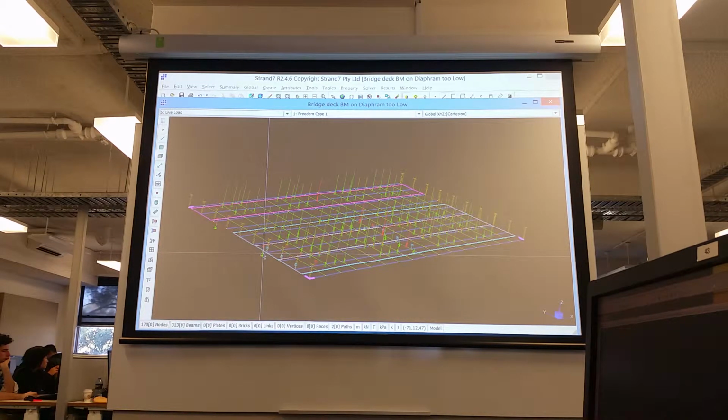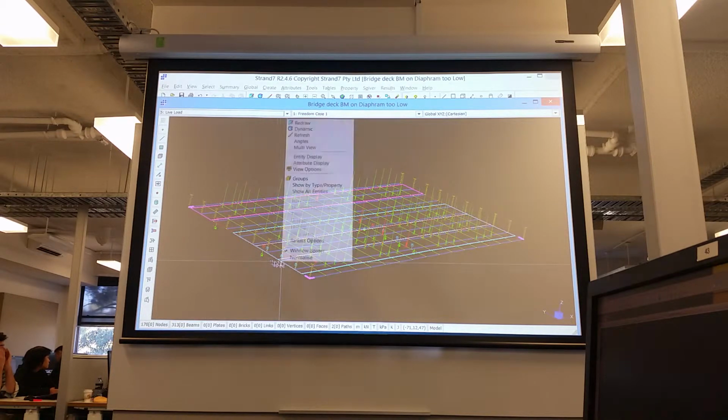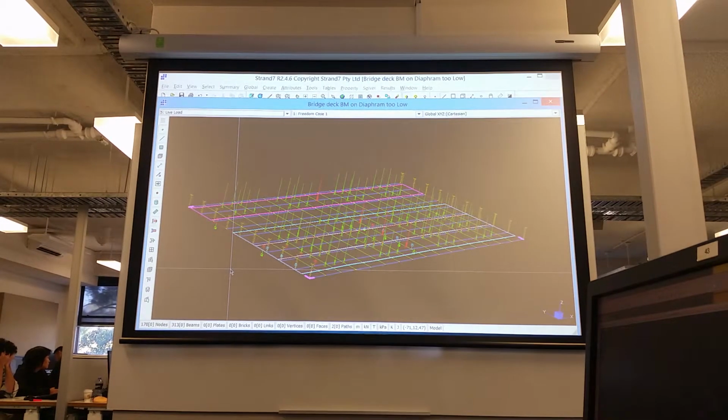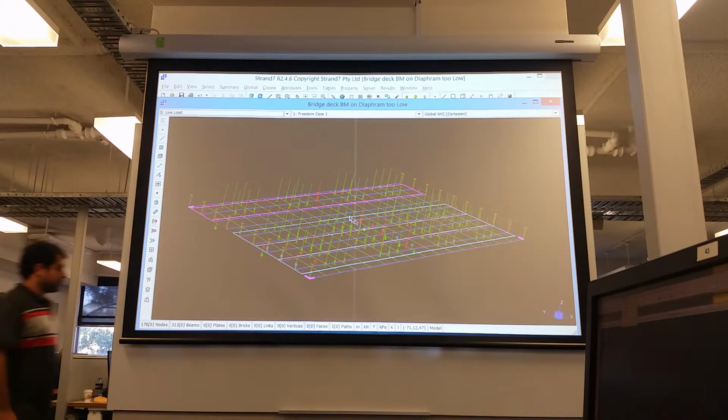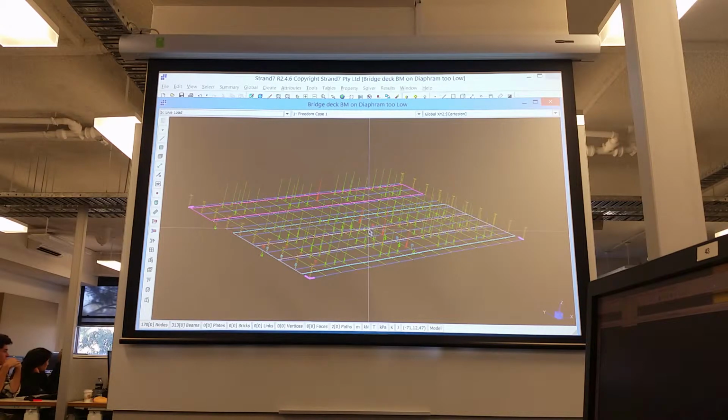And doing that, we find that it's this location here. So then we can insert the response variable at that location. We can either move that one, or in this case I've inserted a new one. And then having done that, we need to go through the whole three-step procedure again. So having inserted some new response variables, we should do the same for the top slab. I believe for the top slab that the locations we originally used were the correct ones.